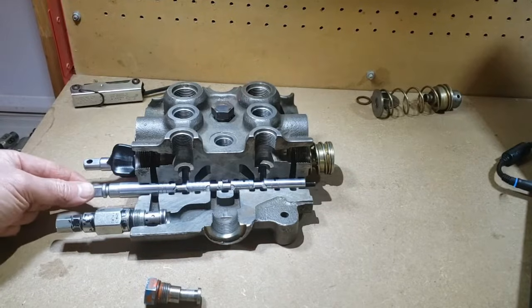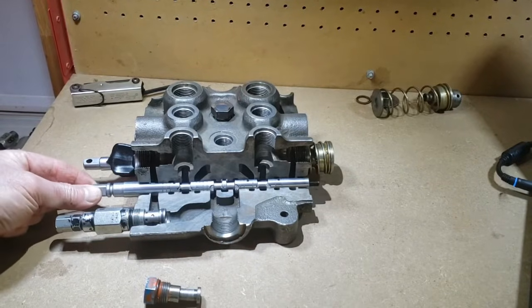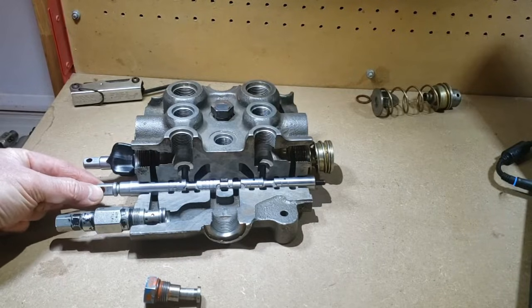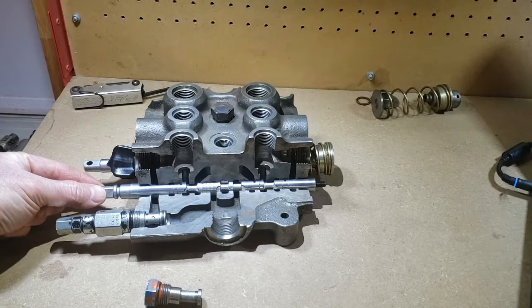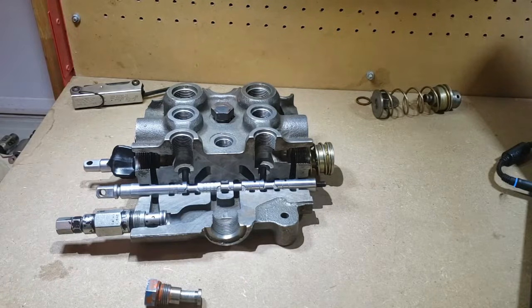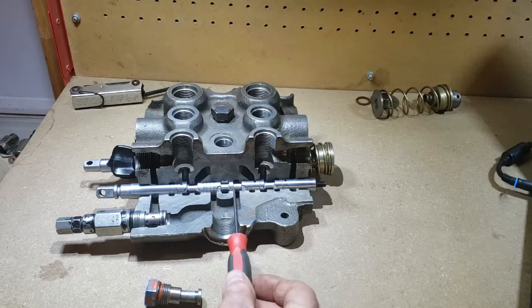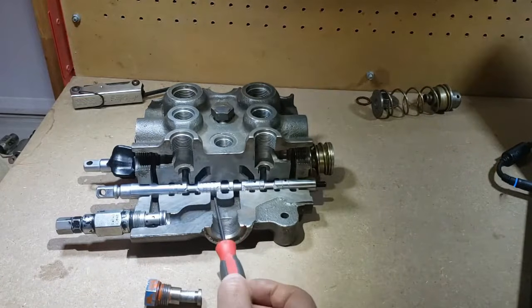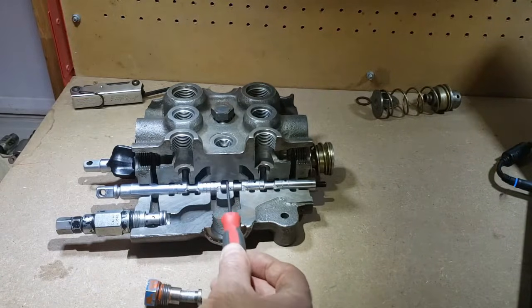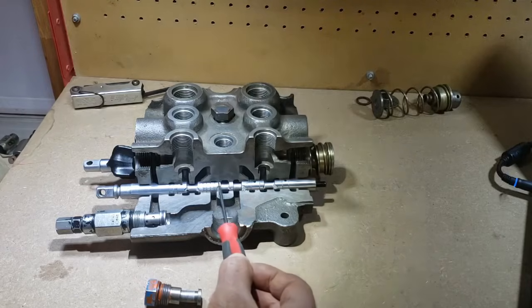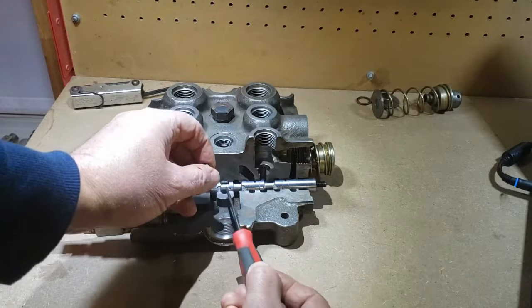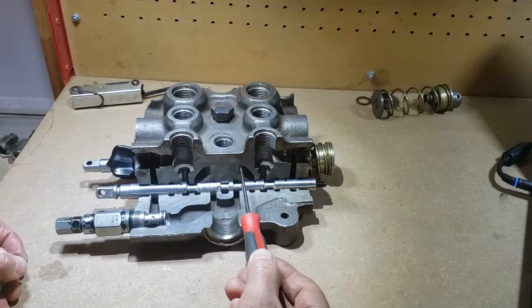So let's look at what happens when we go to the lower position. Again, if I put the control valve back in hold and then I move it the other way with the linkage, there is the lower position where I want to lower the loader frame down. So now again, pump flow comes in. Once again, it's blocked at the open center flow path. We've got no way the oil can connect to this open center path. We've got a land blocking it here and a land blocking it here. So again, oil's going to back up and open that same load check valve, and it's going to flow into the bridge passage again.